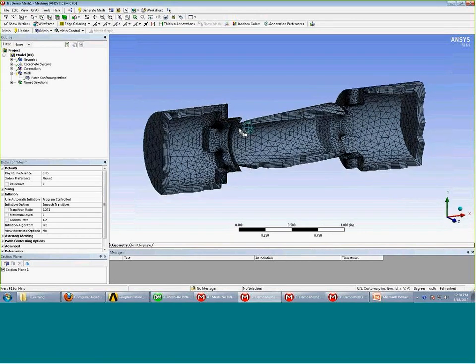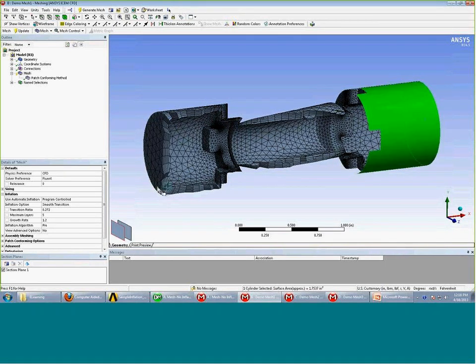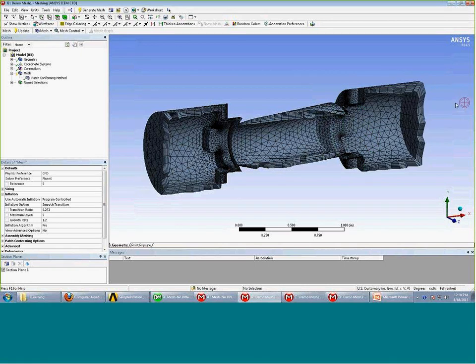But what I really wanted to do over here is construct a flow-through mesh. And here, these two faces also have been inflated, which I don't desire. Now, if you remember, I talked about how you can use name selections in order to control where the meshes will be generated. So let me just demonstrate that.